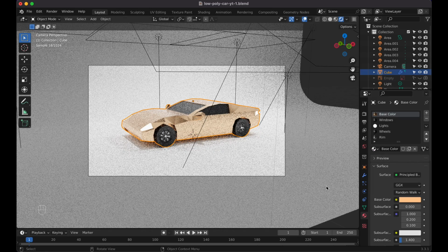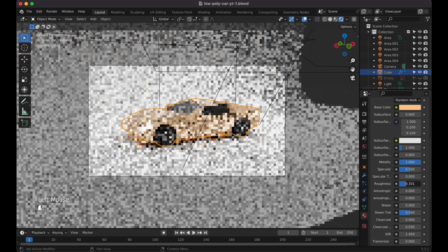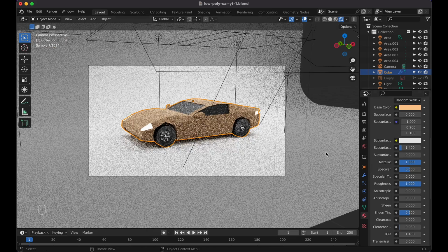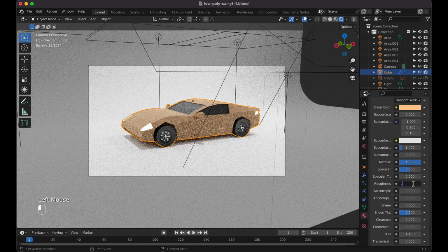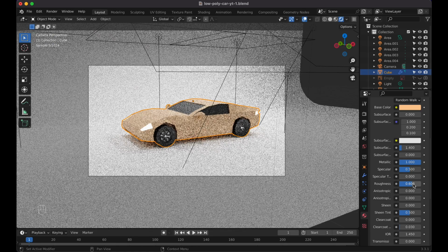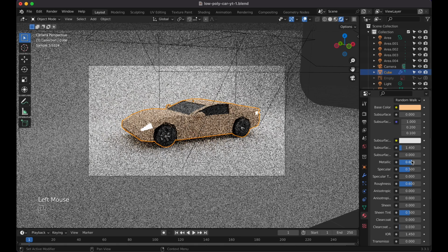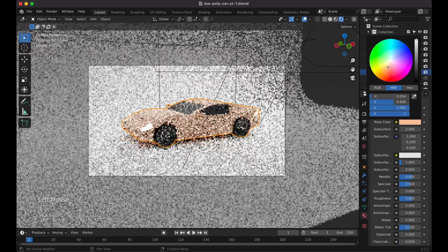For the most part, the shiny part is really what's making this side look the way it is, so if we change this roughness to full roughness, it's much harder to see. Again, it's all preference, but let's just do 0.6 now, metallic 0.6, and then basically we'll change this up.